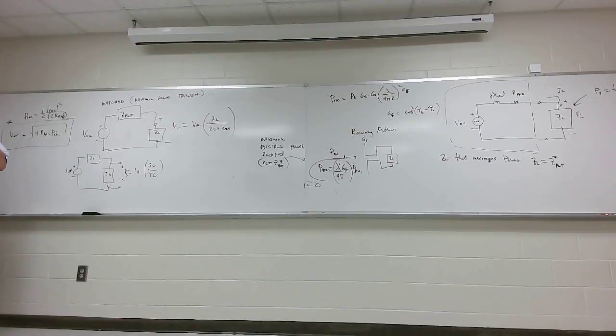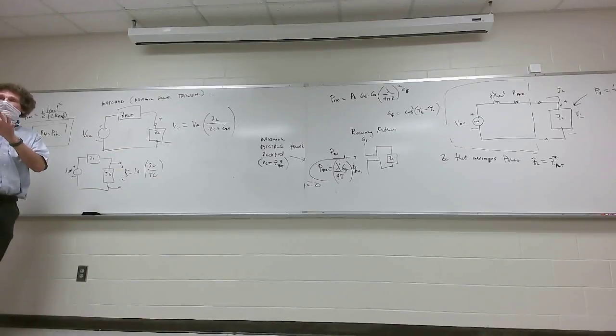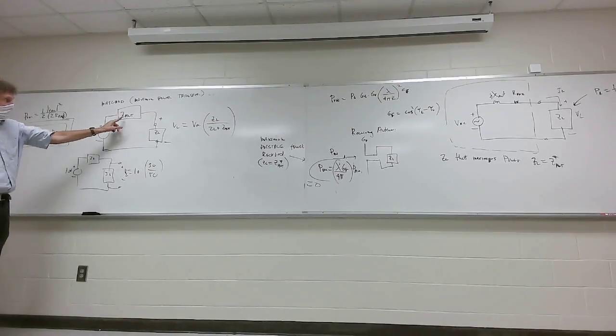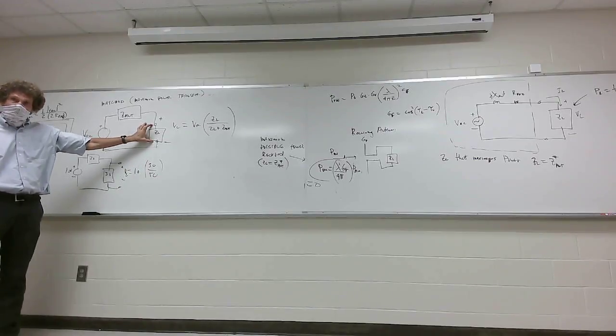No, no, hear me now. This is a great question. This is where people mess this up. We assumed that the imaginary parts had no effect with the optimal power transfer. That was the assumption, okay? Now, you have to use the entire antenna impedance here if you want to calculate the actual current that would be developed across any load value, or the power. You follow me on that?